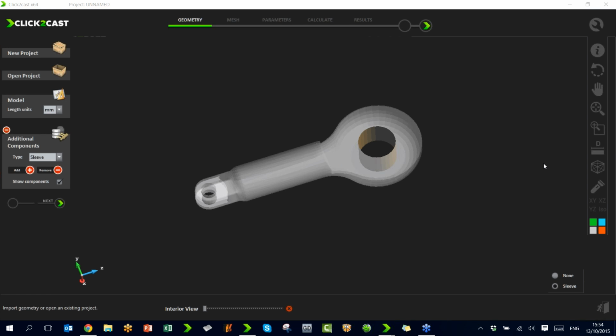Siyong is asking whether calculation time depends on the total number of cells, such as when some areas are very thin. Yes, in fact the calculation time depends on the number of elements or the number of cells. This means that if you increase the number of cells, calculation time will increase, but also accuracy will increase. If we are using a low number of tetrahedrals or elements, calculation time will decrease, but accuracy will also decrease. So this is a question of a balance between calculation time and accuracy.